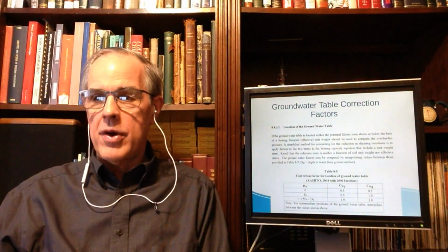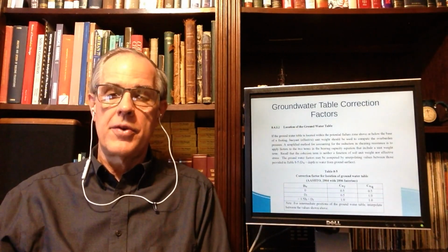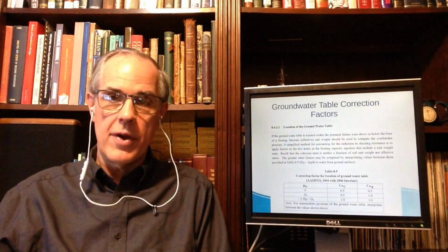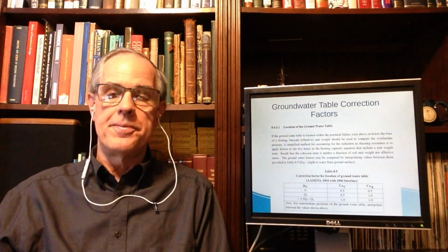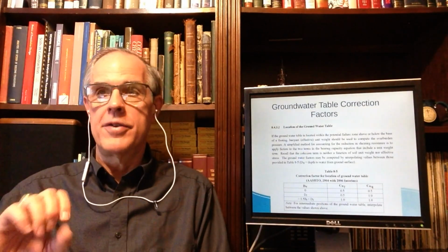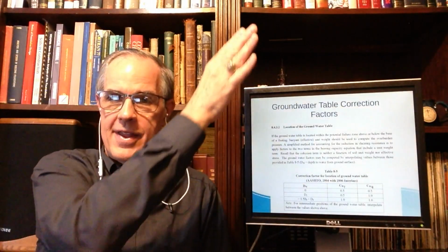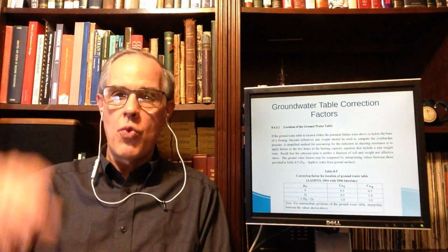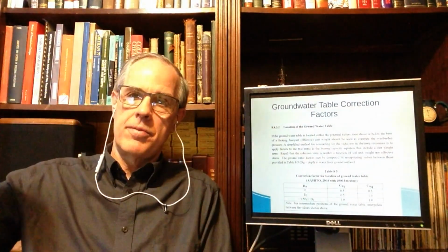If you have the groundwater surface at the depth of the foundation, groundwater does not affect the soil overburden, but it does affect what's below it, the soil weight, and how much it affects the bearing capacity. Because, the soil weight, basically you've got a curved surface that looks like this. There's a soil mass that's trapped in there.